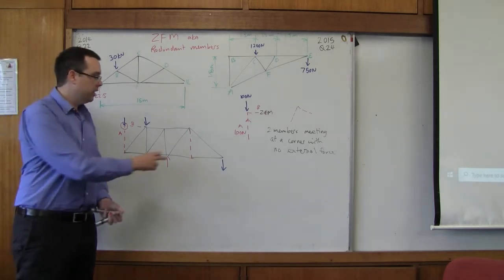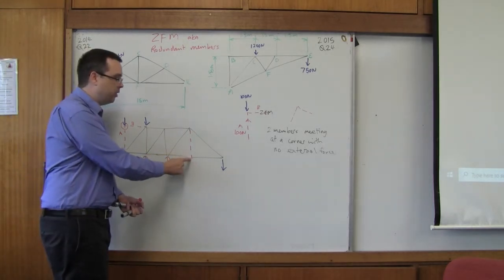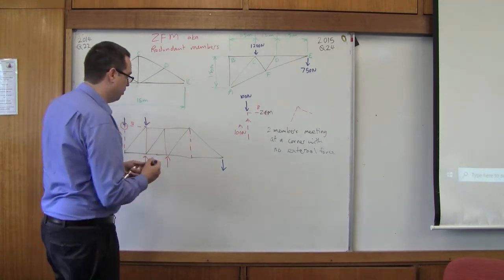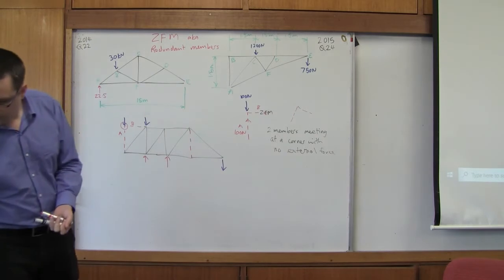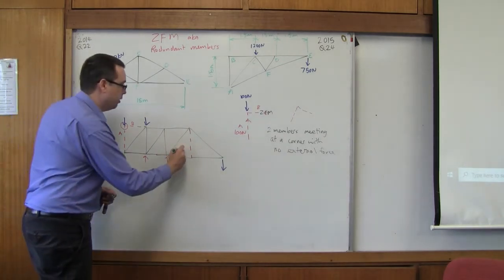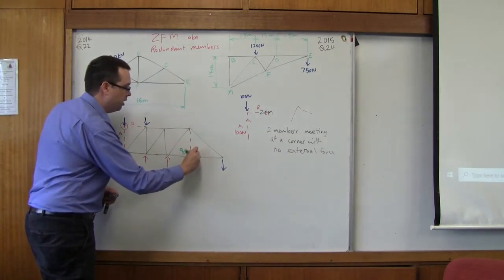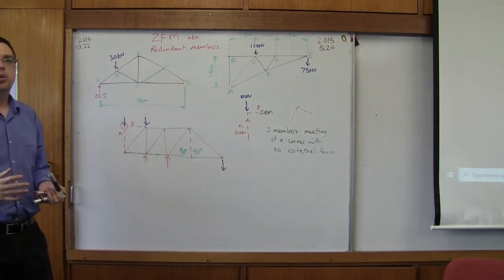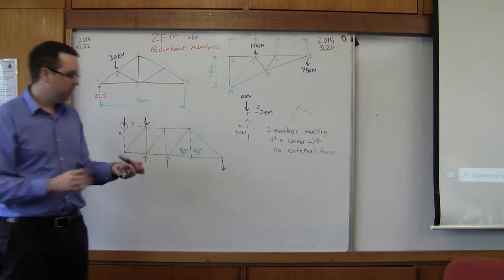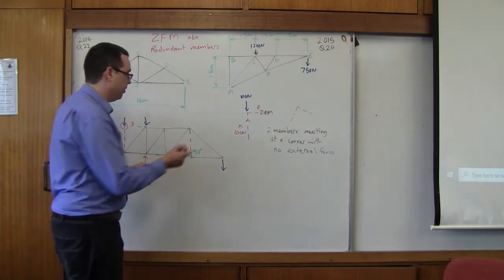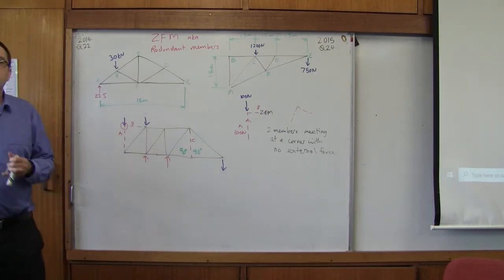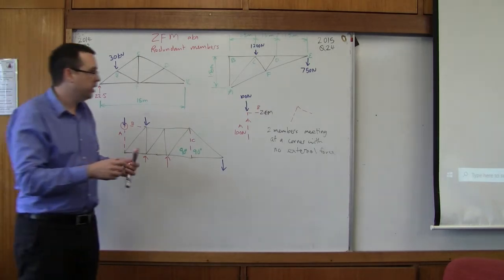So see how here this makes up 180 degrees. In this case, it's pretty easy. I can use green for this one. We've got 90 degrees plus 90 degrees, it's going to equal 180 degrees. It's the same situation if we call this C for the sake of argument. If this member C has any amount of force whatsoever, there's nothing to hold that joint in equilibrium.